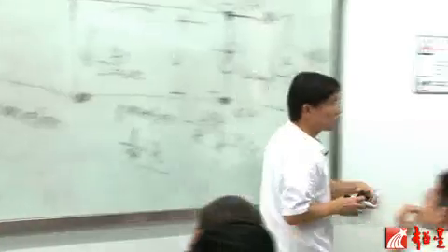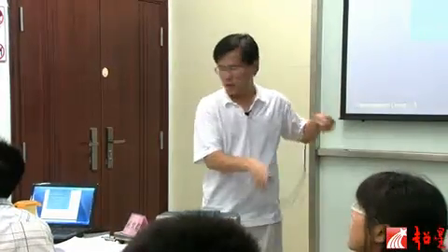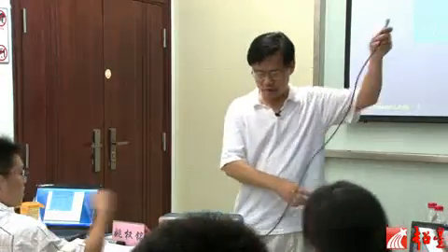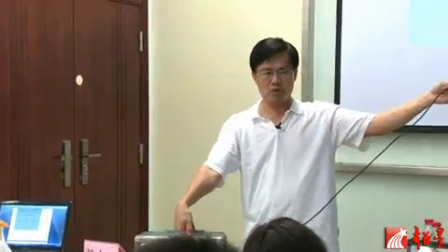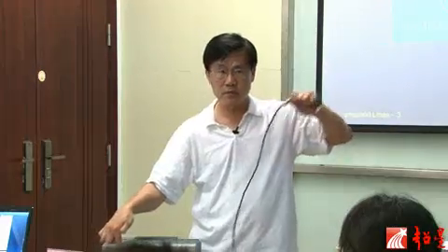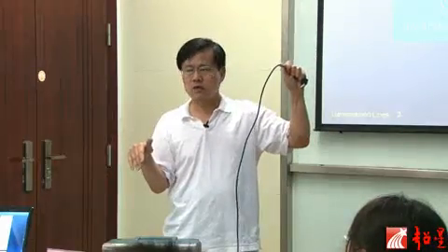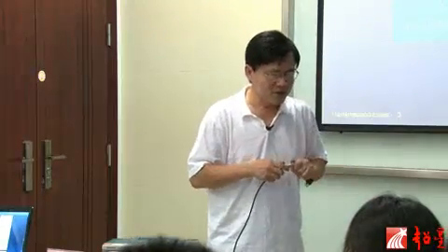That's why, can I borrow your key again? See, the voltage is 0 at this point right now because this is one quarter wavelength away, right? But if I short circuit here, you can see that I get this voltage there. So we have to use wave propagation to explain this.